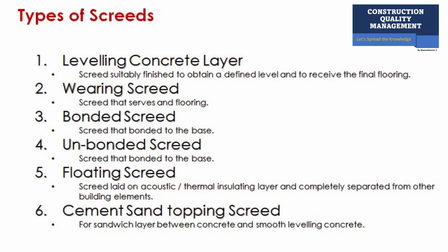Generally this will be used for obtaining the finished level, and above that the final flooring. Then wearing screed. Wearing screed itself is, as it says, a final layer; nothing will come on the top, and foot traffic or mild vehicular traffic will be allowed on that.